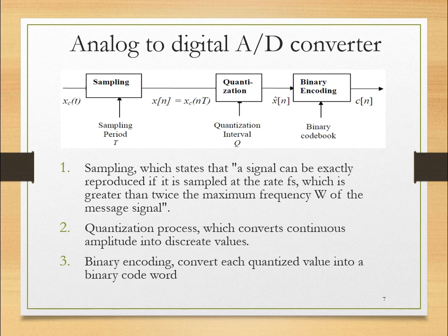You take the value of the signal corresponding to that sample in time, and these should be placed wisely so that you can reconstruct your signal at the receiver after you transmit it. And what was the condition to do that? The sampling frequency should be greater than or equal to the maximum frequency of your message multiplied by 2, in order to avoid interference between the transmitted pulses.